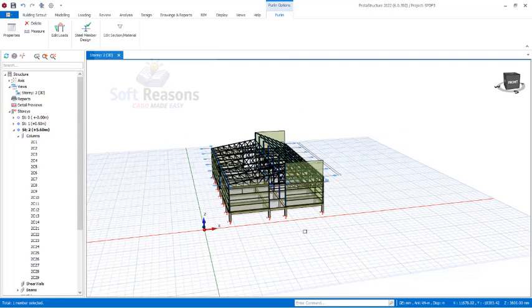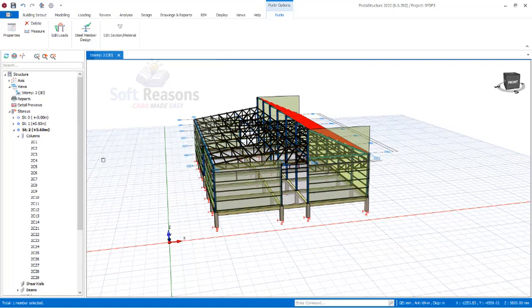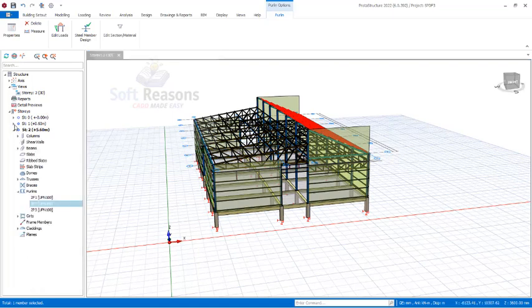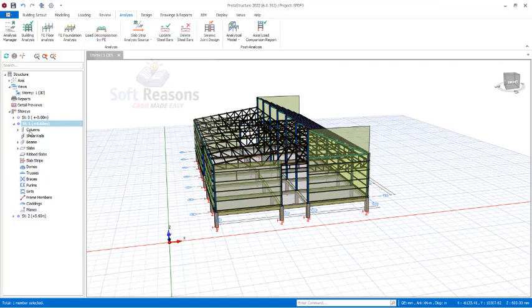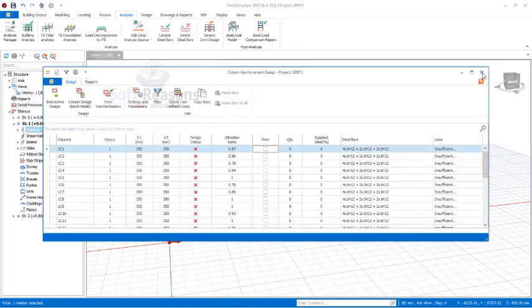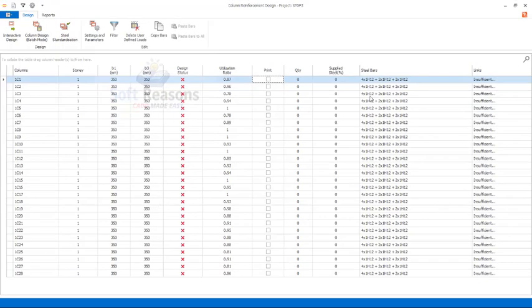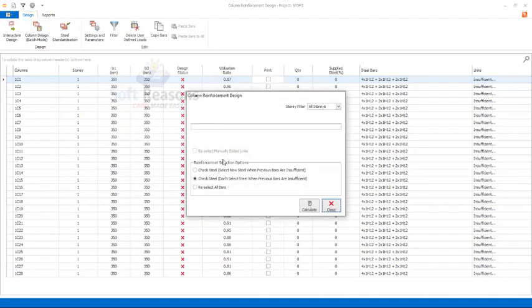let's check the beams and the reinforced concrete columns if they have actually been designed as well. Those columns are found at story 1, so you select this and then right click, and then let's check all the column members. Click right there, and then in the column members you can see all of these have not been designed. But that is not an issue. What we need to do, come to the column batch design right there and reselect all. So it's going to reselect all members and design it again for all the stories of this reinforced concrete columns.